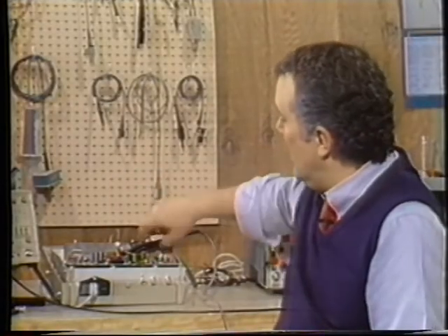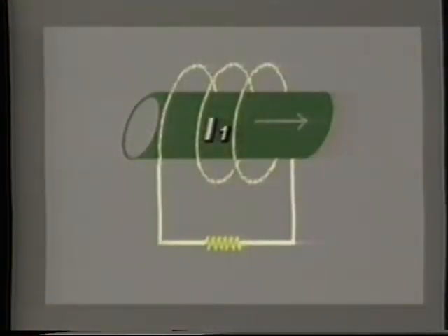Or you could use a current probe, like this one. Current probes convert flux fields to voltage signals by transformer action. So to measure the current flowing in a conductor, we surround that conductor with a magnetic circuit and capture some of its magnetic field, converting that field to voltage by transformer action. The transfer ratio of a current probe is specified in so many volts per amp. By dividing the observed voltage by the transfer ratio, we obtain an answer in amps.